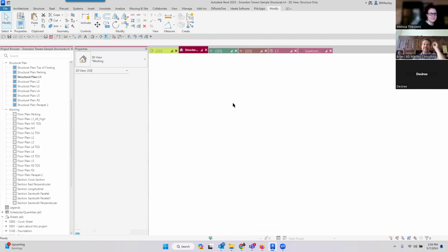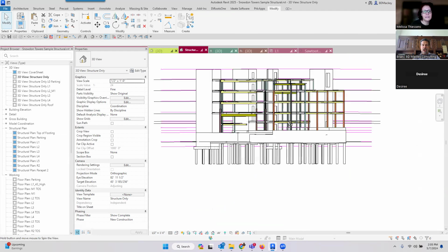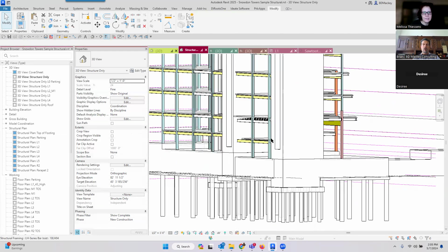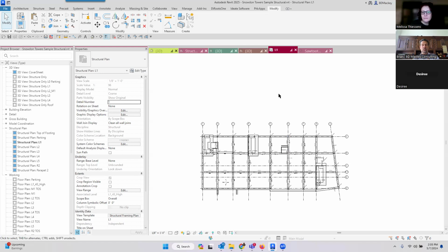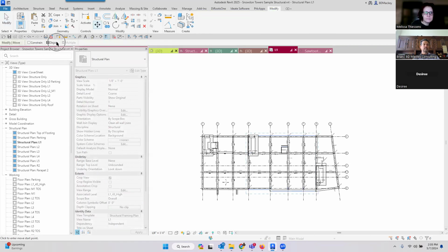So with that disjoin checkbox checked, it basically just disjoins it from everything. I probably lost half of my framing. If I did level 1, I'd lose all the walls associated to it. So it can be really devastating with having disjoin checked, because it will delete your levels, etc. So your question isn't, are you modeling things wrong? The question is you missed that simple checkbox of disjoin.